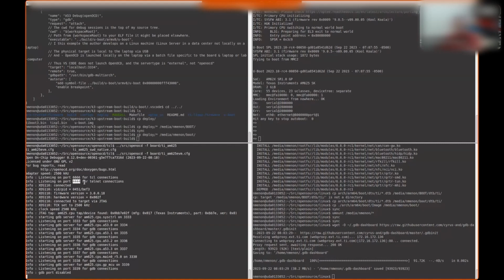Now, maybe you configured it wrong and you have an issue where you think you're writing to a GPIO, but that GPIO is not behaving the way you expected it to. And you are now suspecting that maybe my RAT configuration is wrong. Is the GPIO really programmed? So you can come from the debug SS subsystem and look directly at those registers and say, oh, my RAT configuration itself is broken. Or maybe the GPIO registers are misconfigured for some reason. So this is an escape path that you have with the mem AP port.